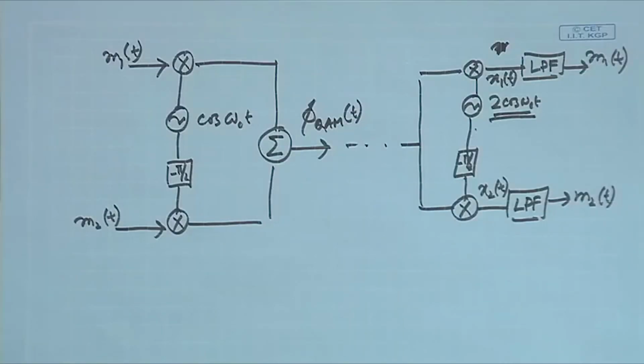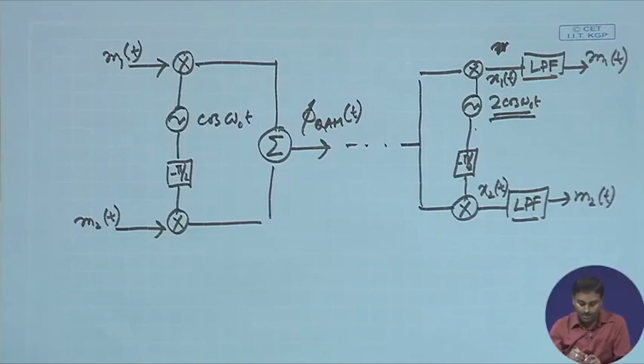But later on you will see that there is a carrier recovery process, because I am doing this demodulation coherently. There is non-coherent and coherent demodulation. Probably I have not talked about these terms, but I have been mentioning them. Non-coherent is like that envelope detector. That means I do not have to generate a local carrier which is synchronous in phase and frequency to the incoming carrier. So, that is called non-coherent. That means the receiver part is pretty simple and I do not have any influence on carrier generation.